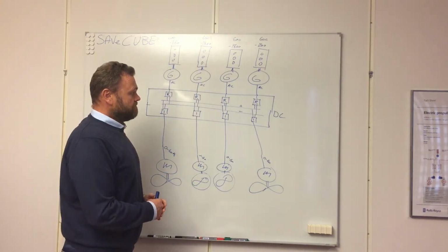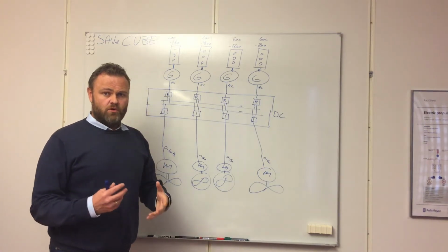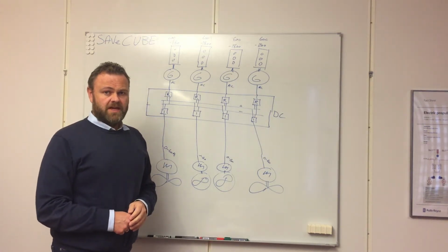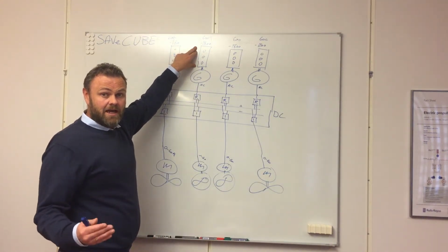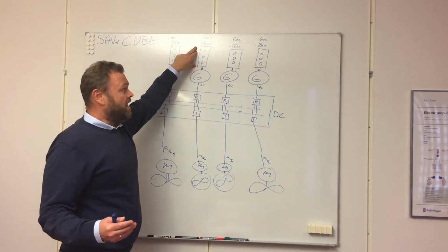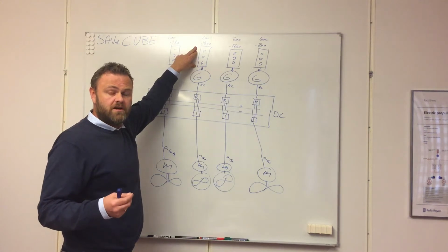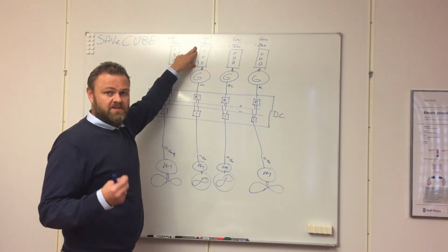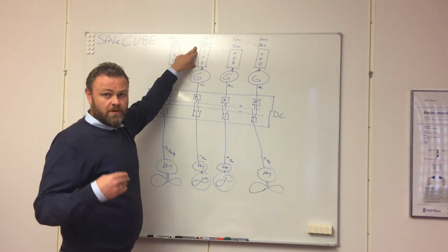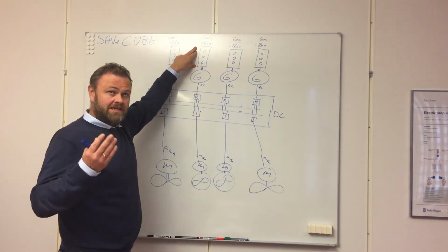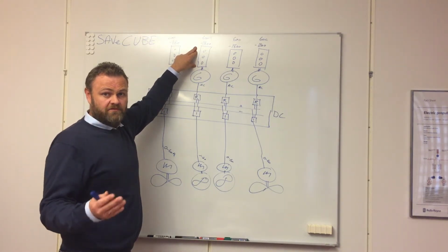Okay, you have fuel saving. You have several more additional benefits from that. You will of course have a more clean and hot combustion. The mean cylinder pressure will be a bit higher, so it will be warmer inside the piston and the combustion. So your exhaust will be warmer, and your cleaning system, if you have that in your exhaust, will as well perform better.